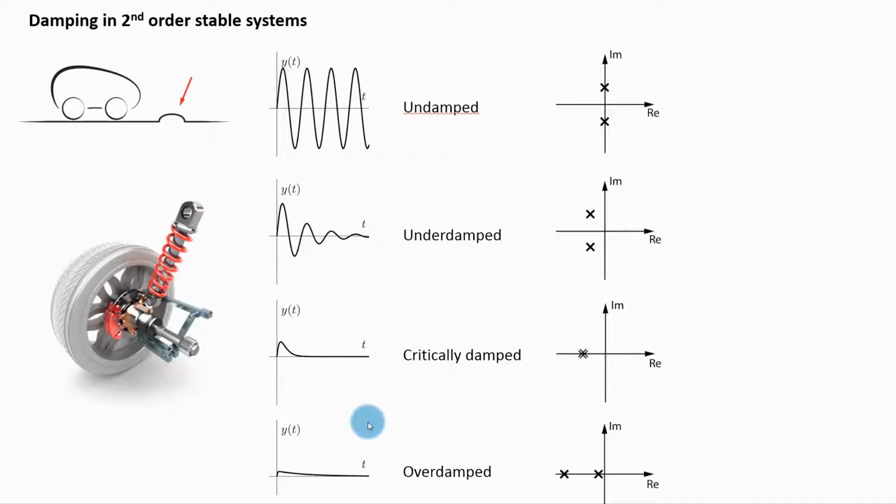Now, what is the difference between the overdamped and critically damped response? Well, if your damper resists the motion too much, it will prevent compressing the spring, so if your wheel hits a bump, the spring will not compress sufficiently and your entire car will jump. Your spring will compress only a little, and then it will return to the original position very slowly. This is what we call the overdamped response. We provided more damping than we had to prevent oscillations.